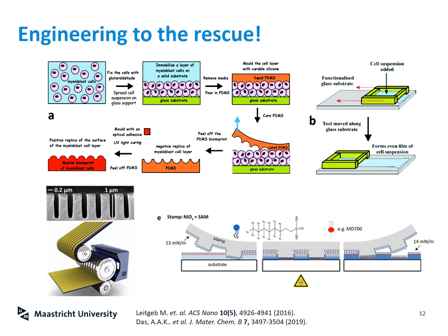Now what you can then do is take another polymer, pour that over the PDMS, cure that polymer, and you have a stamp that has exactly the same dimensions and also some of the functional groups that your original template cells have. And what you can now do is take that master stamp and put it into a roll-to-roll coater, as you see at the bottom picture. Now, a roll-to-roll coater takes sheets of a polymer and passes that over multiple rolls. Now, if you let that roll-to-roll coater glide over this master bioimprint stamp, then you will create stamps as you go along. You will literally create a production belt making large sheets of MIPs.